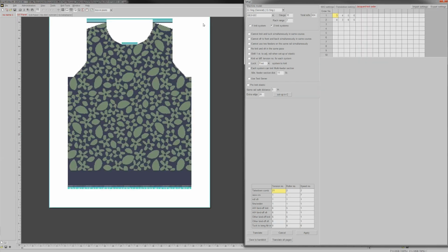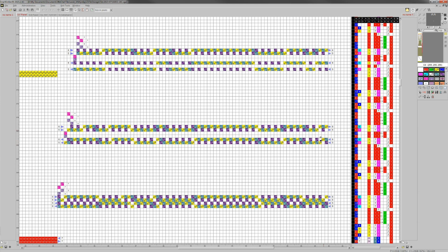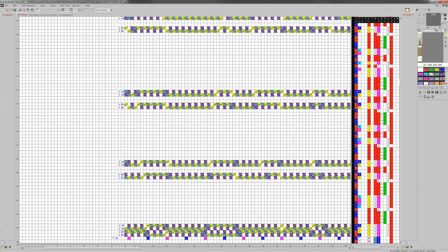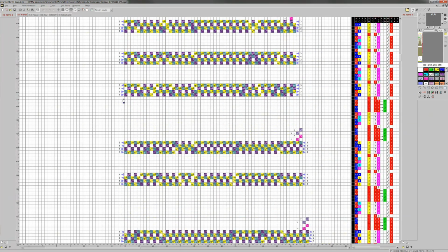For the Jacquard Knit Order tab, we could set different knitting order for the feeders. For example, in Combination 1, the feeder order is 3, 4, 5, 6. In the option line layer, we could set which combination of feeder order we use for each course. Let's check the feeder order in the machine code. In courses that use Combination 1, the feeder order is 3, 4, 5, 6. While in courses that use Combination 2, the feeder order is 4, 3, 6, 5.